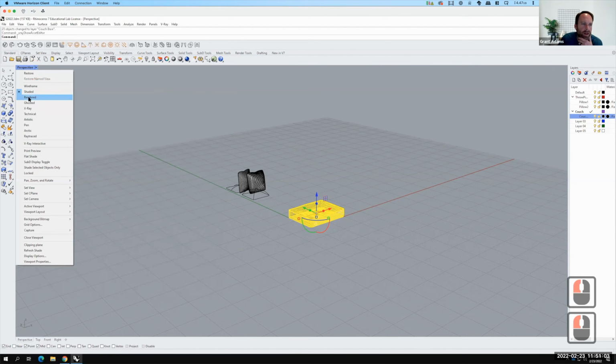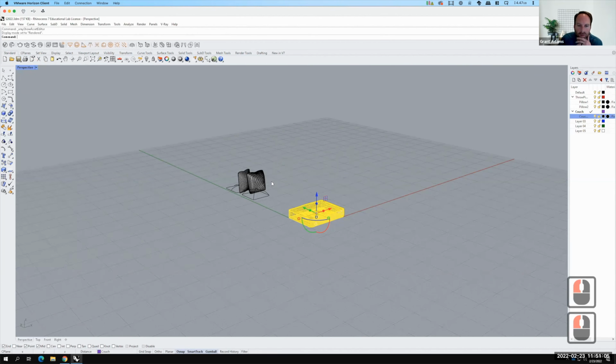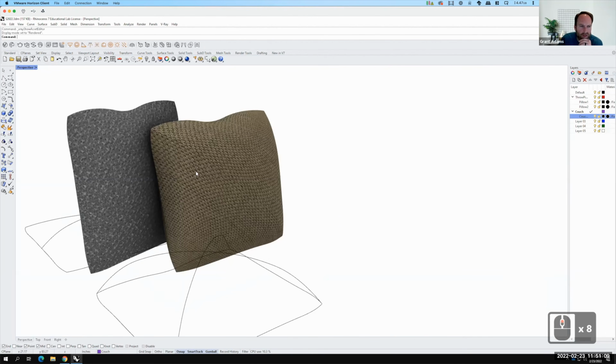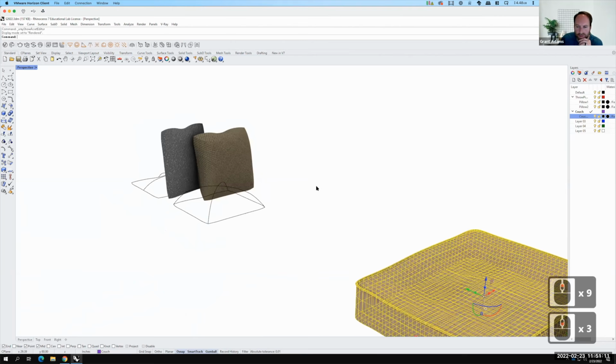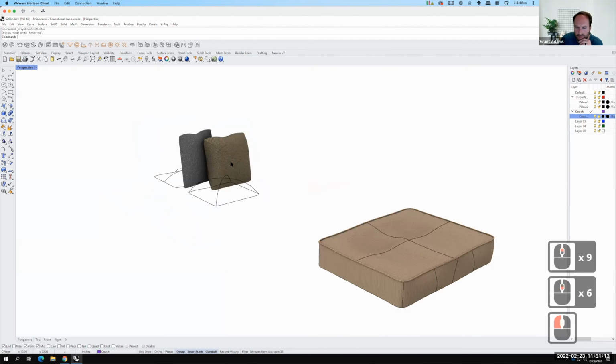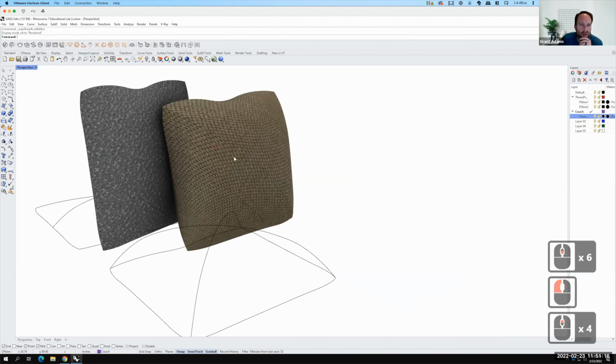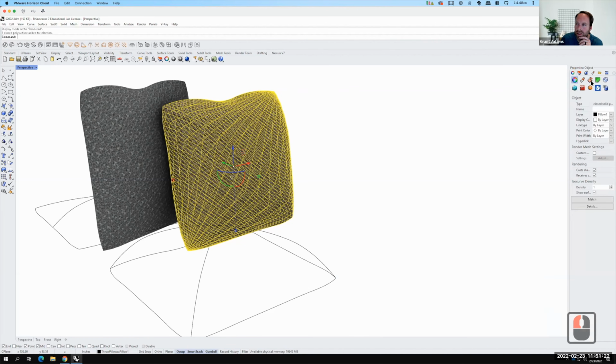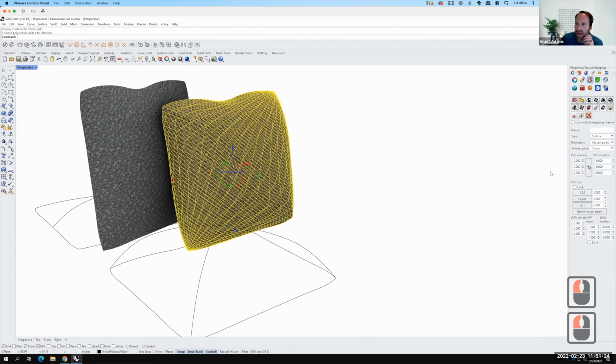So if I went into my rendered mode, we could check what the look looks like here. So we may need to do some texture mapping, which isn't really a surprise. So on this one, let's go ahead and go into our properties. Let's go into our texture mapping. And really, this one could be a bit challenging. A box isn't really relevant. I would say a planar mapping or a surface mapping are probably best. I'm going to do a surface mapping on it.